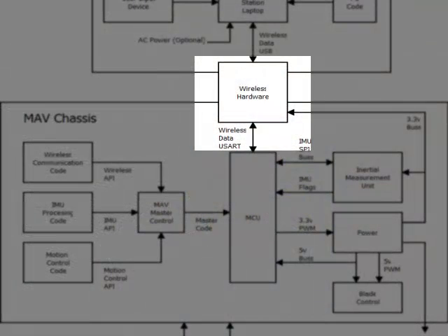There are three alternatives considered for the wireless hardware. A hobby RC transmitter, which is relatively expensive, difficult to interface with, and does not offer any options for sending telemetry back. The Zigbee protocol has a longer range than either of the other two options, but requires a module at either end and offers a relatively low data rate. Wi-Fi needs only one module, as Wi-Fi is present in many consumer electronic devices already owned, and has a relatively high data rate.